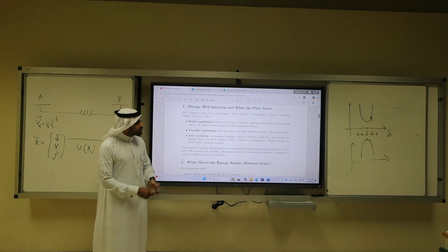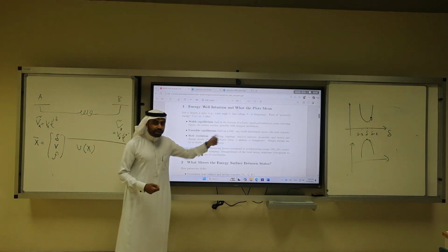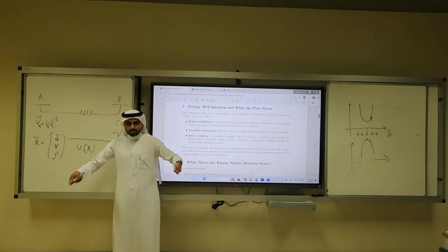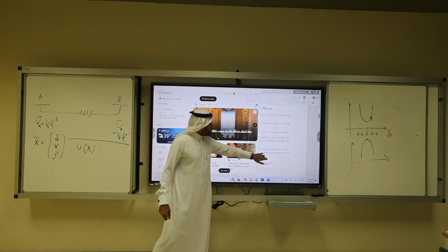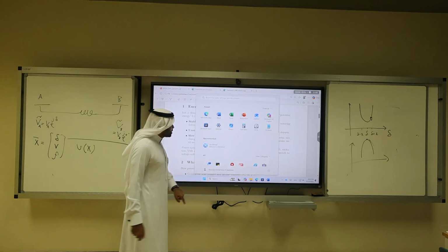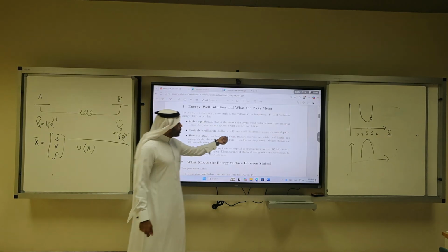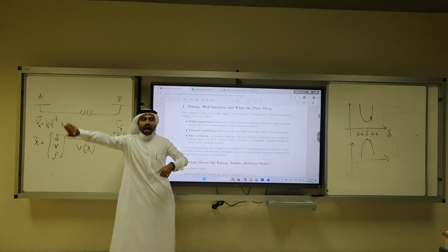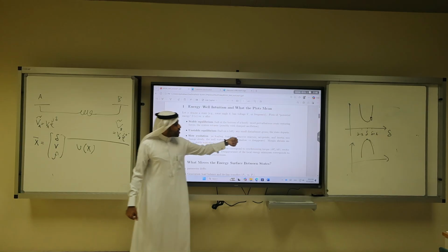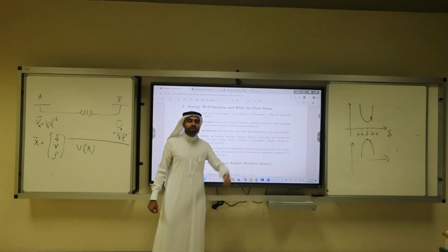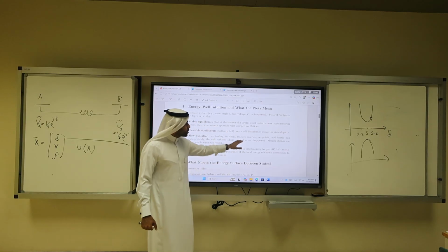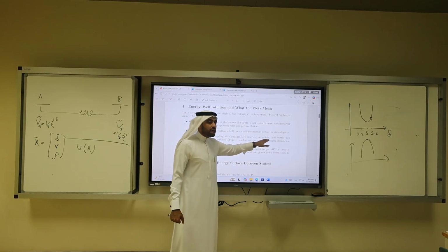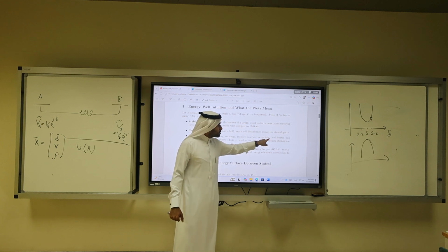What is meant here is that as loading increases, the more loads we add to the system, the topology changes. We connected more lines. Or reactive reserves: we have capacitor banks connected. Or shunt reactors connected. We change the set point of the generator.